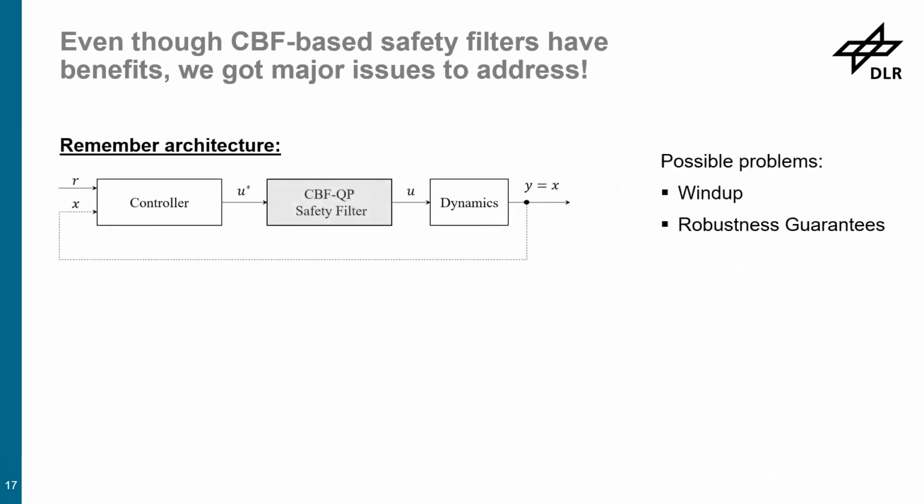If you're just placing the safety filter right behind your controller, you have immediately one big problem, right? If you're having your controller that is trying to track a reference, and then have a safety filter here, in most cases these controllers have integrators, right? You have a PI, maybe PID, I don't know. And it tries to force following the reference.